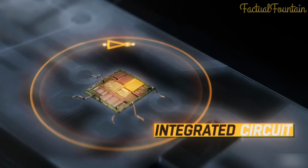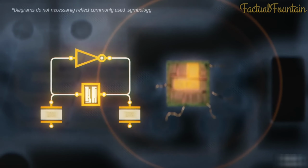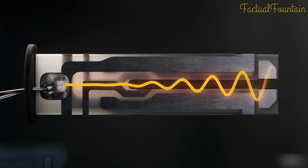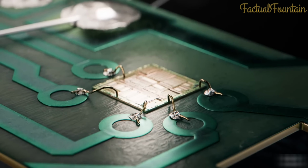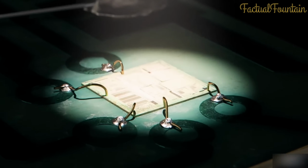To do that, we use an integrated circuit with an inverter to form a feedback loop and two capacitors to assist in the timing of the voltage from the inverter and feedback loop, thus producing a resonant movement in the crystal. This is a rather complicated circuit to fully explain, but here's one way of thinking about it.